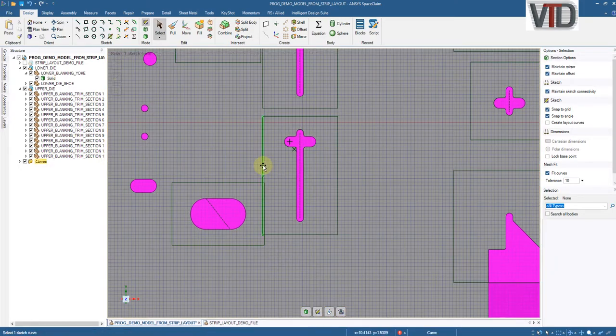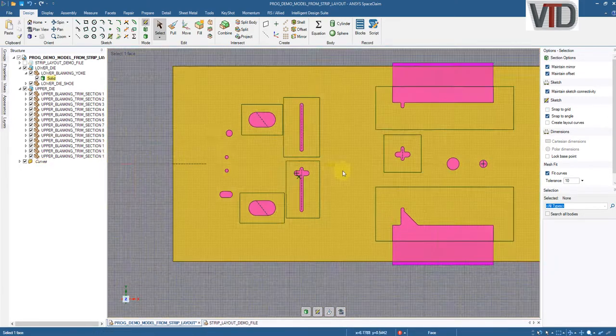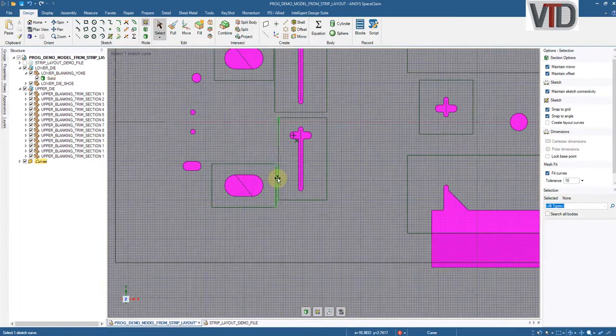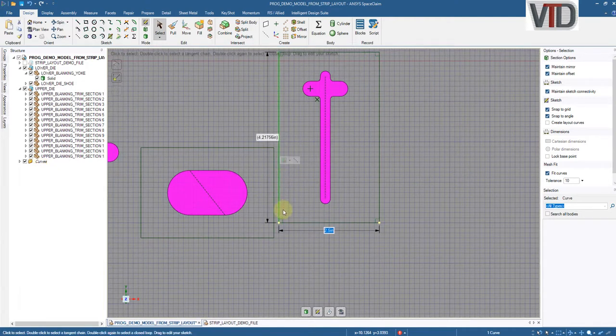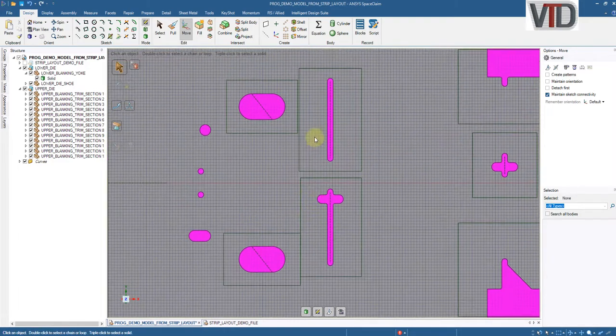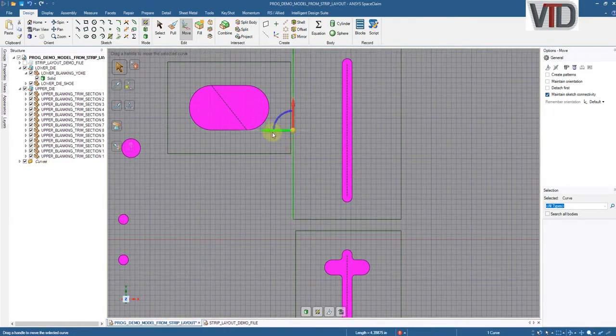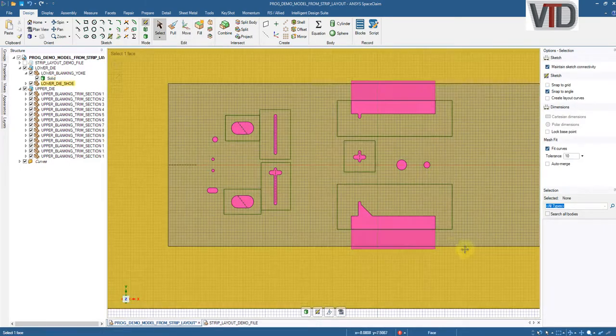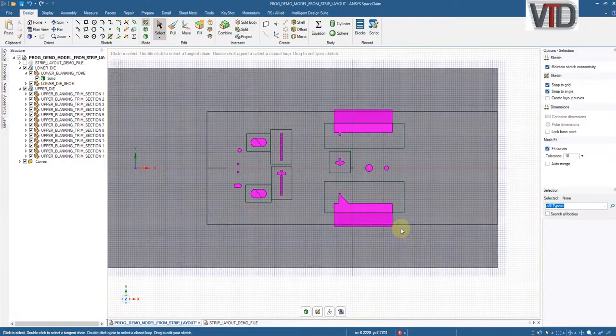I'm going to go ahead and resize this so that none of these blocks are actually touching each other at this point. I could have them touching each other actually, so just to be clear about that, I could move this. If I use the move command, I can click on a line and press M to move. I can pick this, I can move up to there. I could pick this one, and I can move it up to there. It's not going to hurt anything. I didn't want you to get the impression that I was trying to keep them separate from each other for a specific reason. It wasn't.